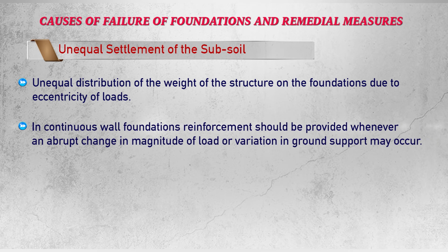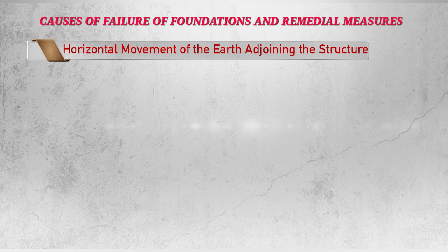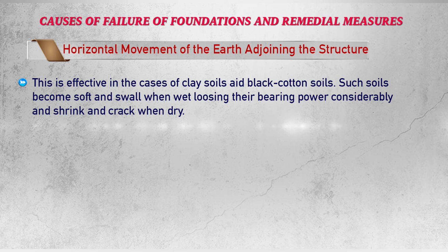In continuous wall foundations, reinforcement should be provided whenever an abrupt change in magnitude of load or variation in ground support may occur. Then horizontal movement of the earth adjoining the structure. This is effective in the case of clay soils, black cotton soils. Such soils become soft and swell when wet, losing their bearing power considerably, and shrink and crack when they dry.